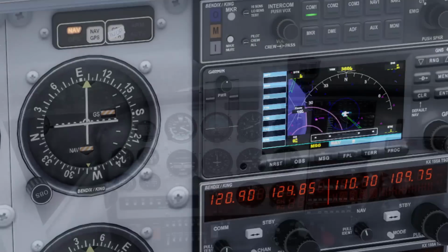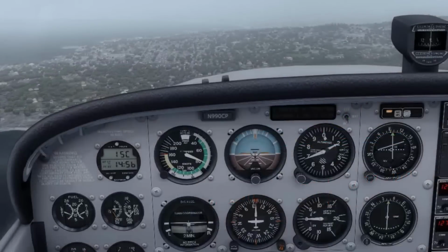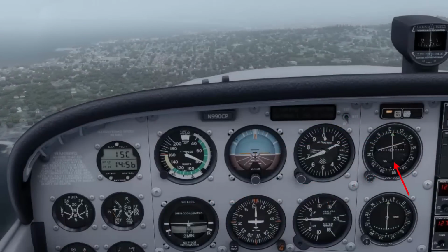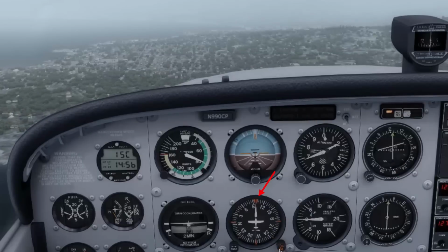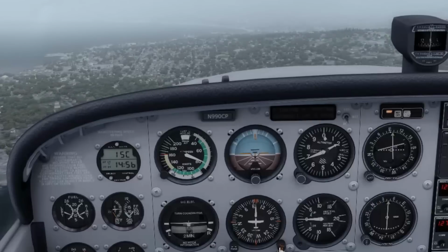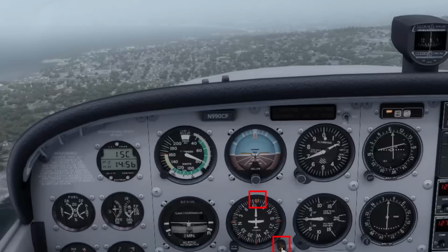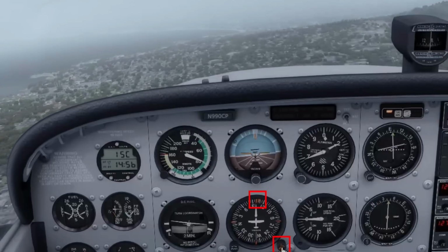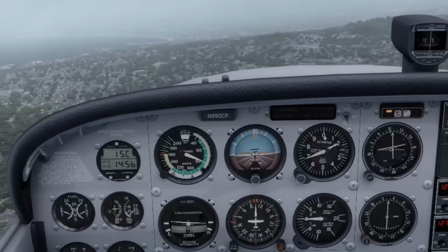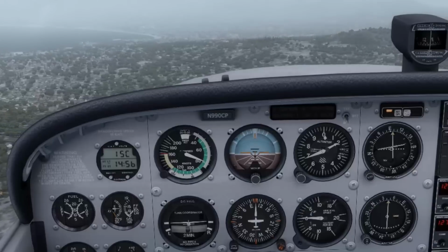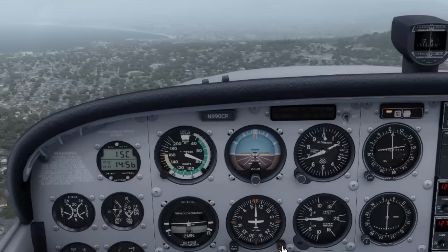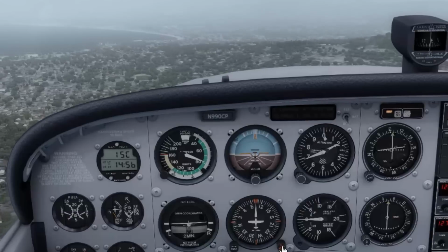I'm going to give a quick example in the cockpit. The localizer course is a little to our right. Because I'm flying a bit more to the right than the 98 degrees course, I will intercept it. If you fly it manually, set the heading bug to the course heading and use it as a reference. The autopilot is in heading mode and I alter the heading bug to intercept the course.